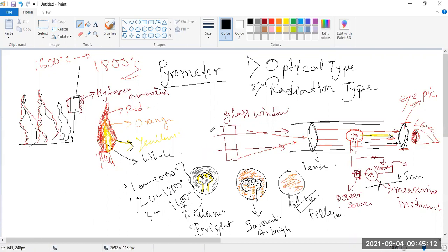So in this way, we can measure the temperature of the furnace by using this optical pyrometer. But you can see the accuracy of the optical pyrometer is very low, because the temperature is rapidly changing, and between 1000 degrees and 1200 degrees there is no measurement position. With a thermocouple or RTD or any thermistor, we can measure a 1 degree change or 5 degree change, it is observable. But in this case, a change of less than 100 or 50 degrees centigrade is not measurable. This is called the resolution, the smallest division that can be detected.